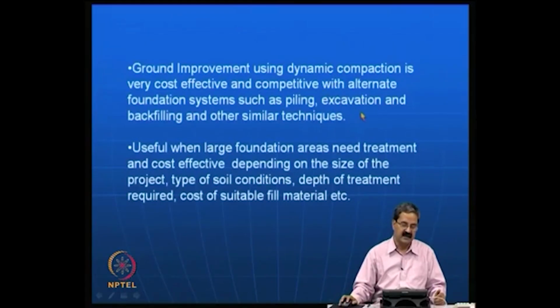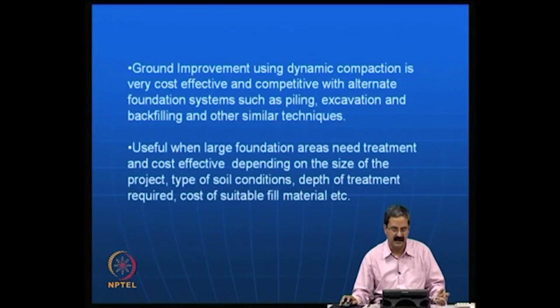So in this case the technique was very effective and cost effective. In fact it is maybe 40% cheaper or even 50-60%, because piles are expensive. Compared to just tamping, where you do SPT tests and all that, what we are trying to do is improve the soil as it is, rather than removing the soil and putting in an RCC and some piles and all that, which is not efficient.